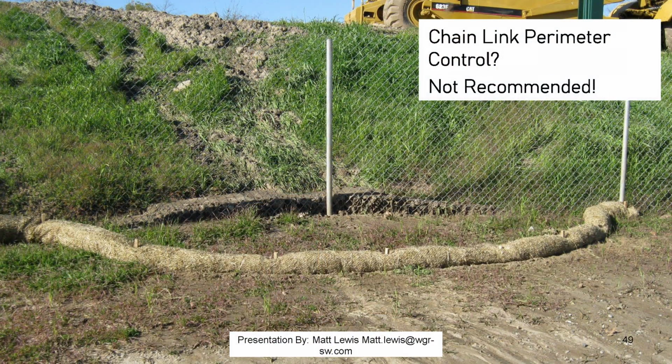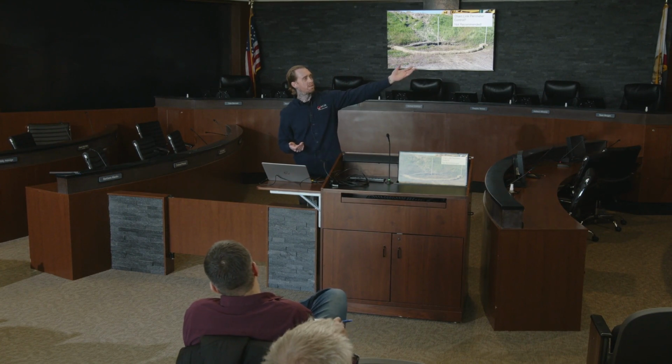And then as it's eroding down, that's where you're getting the velocity, which is creating essentially what will be soon enough rills, right? You can sort of see those channels starting to develop. And so you would probably want to have even a linear control there to prevent the velocity from speeding up. And their solution to it all was throw a fiber roll down at the bottom, which, okay, they're trying.